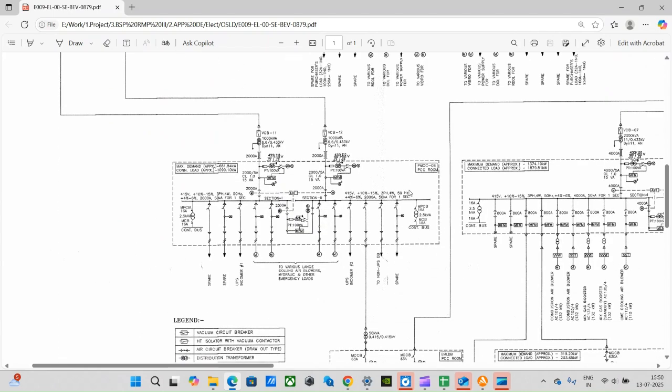But in case of PMCC, this is called power and motor control center, which means it has power feeders. Like, see, it is going to the UPSDB. There are many places in the plant where uninterrupted power supply is required, and for that we need to give a power supply to the UPSDB, from where it will go to the UPS and outgoing distribution of the UPS.